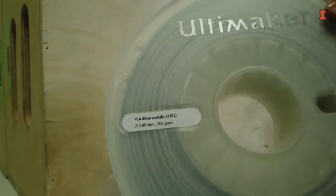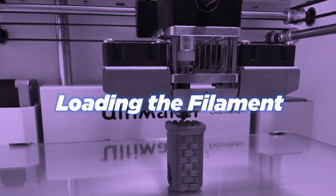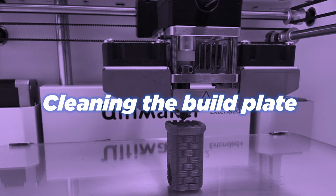If I wanted to shift to another nozzle size, or if I was setting up the machine for the first time, I'd go through a different process. I'd go through a process of removing and installing new code or running a manual build plate calibration process to confirm that everything is at its greatest baseline for printing.